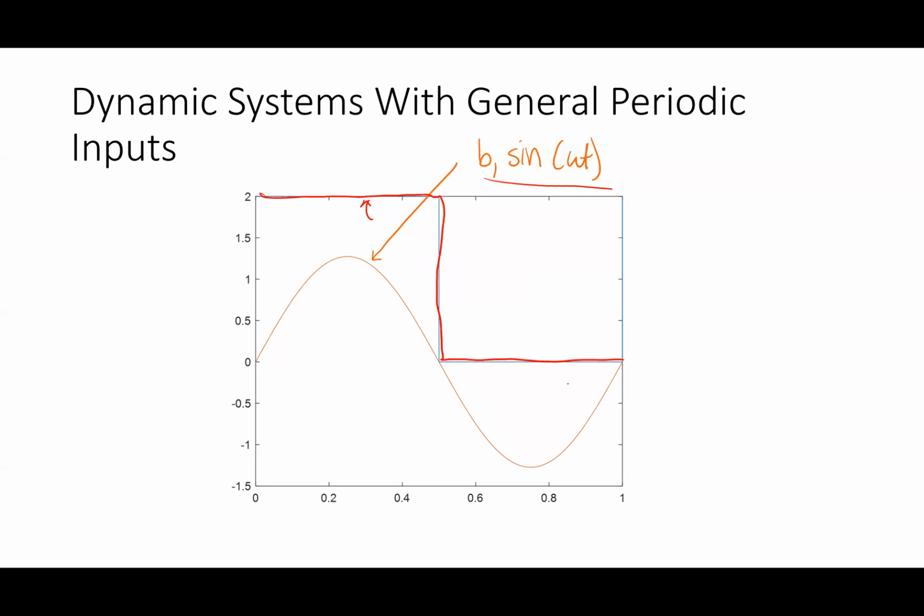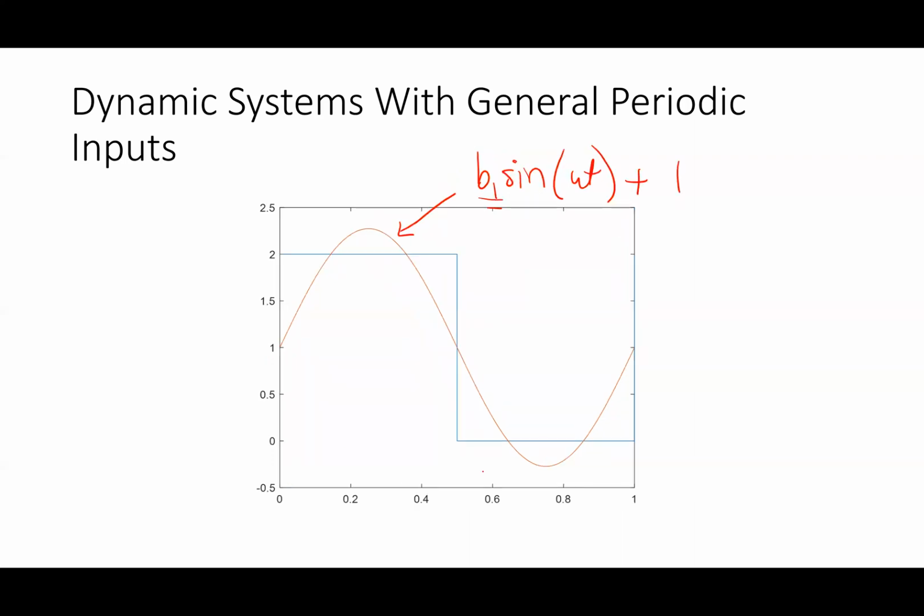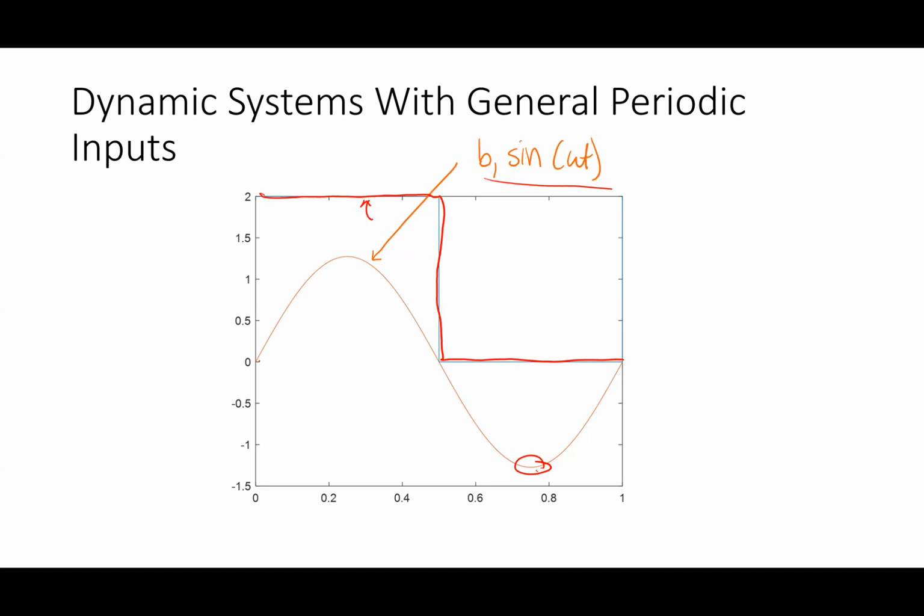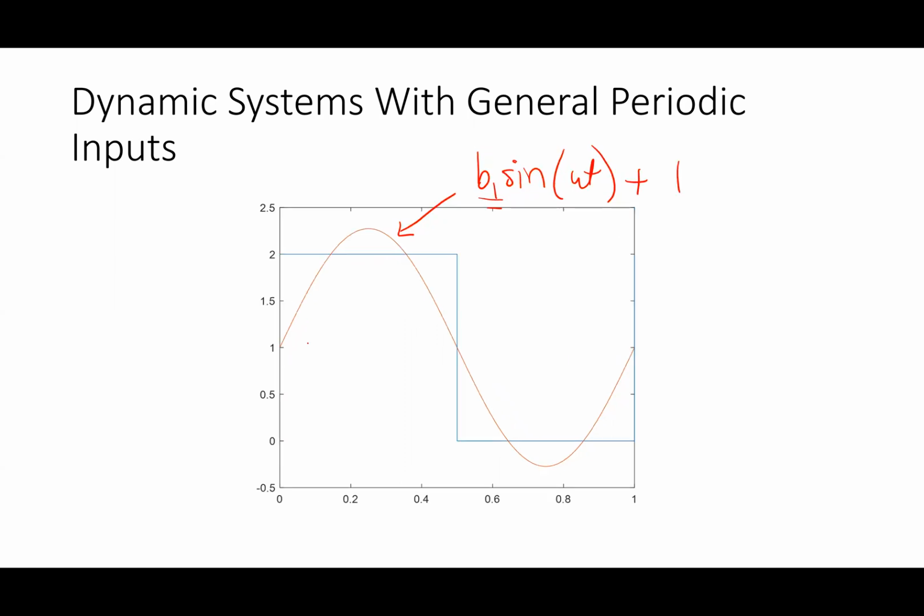So I shifted the sine wave up. If you look, the sine wave's valley here is somewhere between -1 and -1.5. It's shifting up, so it's a little bit between 0 and -0.5. I say I shifted it by 1, you can see this guy was centered around 0. Now it's centered around 1. So I added 1 to that. All right, I shifted that up. Sometimes in circuits we call that we biased it. We kicked it up a little bit.